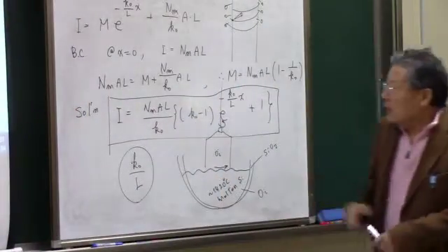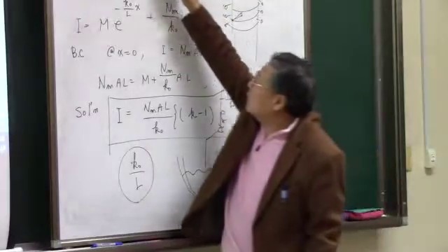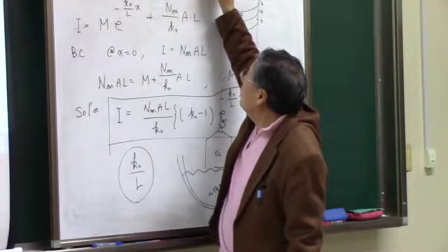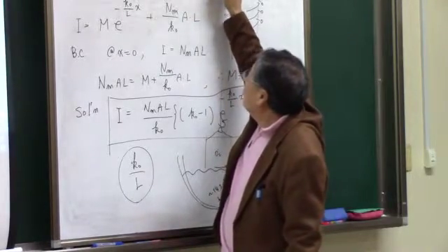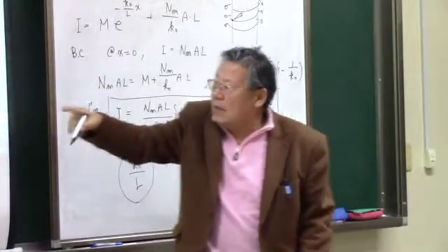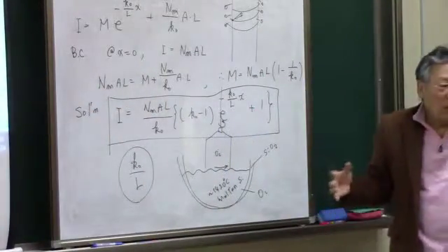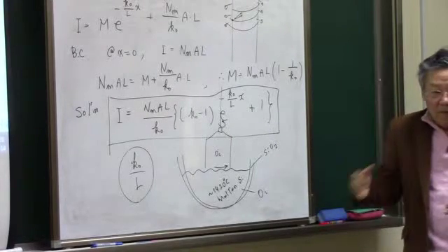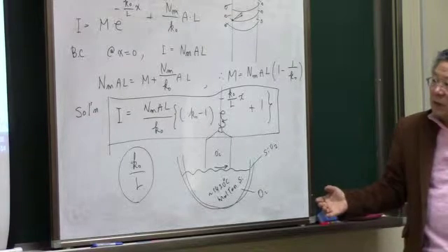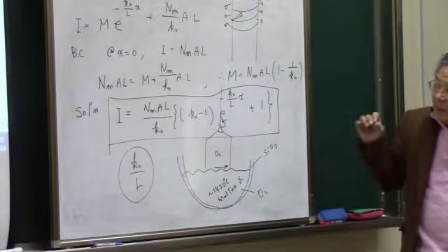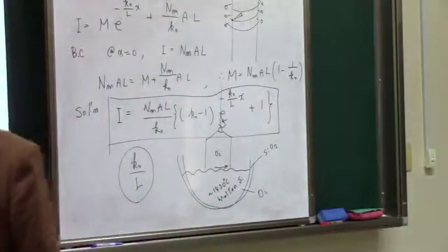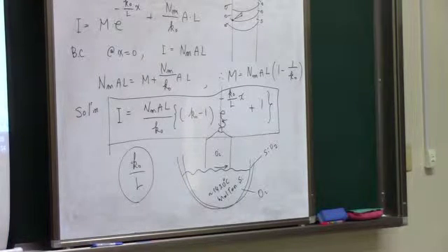The absolute number is big, but if you think of single crystal silicon, the atomic density is about 5 times 10 to the 22 atoms per cubic centimeter, and compared to that, that is just less than ppm order. But electrically, it affects the electrical properties of a single crystal silicon considerably. So it is not a trivial question at all. So if you want to have a really, really good single crystal, you have to go for the float zone technique rather than the Czochralski.